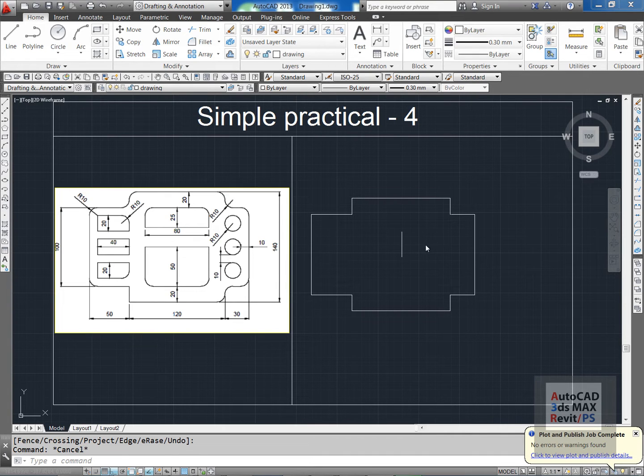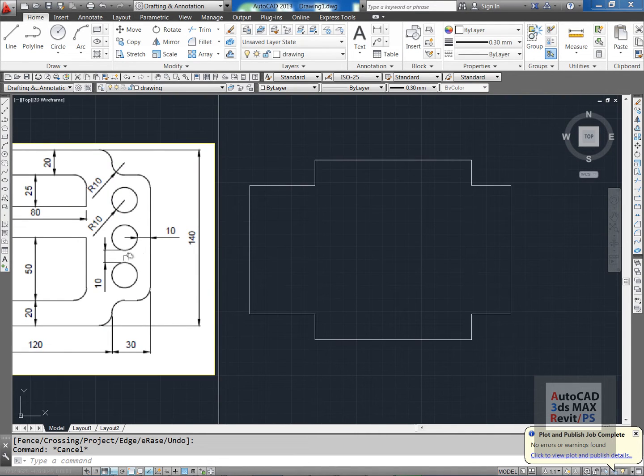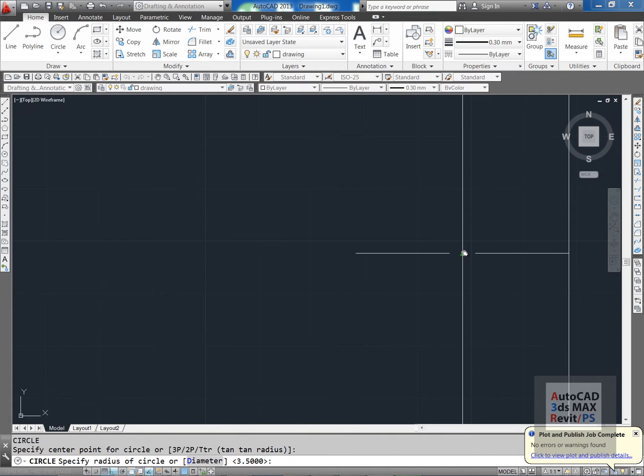So this is how you have made the outer structure of your drawing, and now we will see how to make these circles. For making these circles I will make the view a little bit bigger. Now making this circle, there is a little trick which you have to remember. I will start with this center circle. I will make one line from the midpoint of this. Now you can see the radius of the circle is 10. When the radius is 10 and from here to here the distance is 10, the radius will be another 10. So that means the center of this circle from this point is 20: radius 10 and this distance 10, 10 plus 10, 20. So I will make an offset of 20. I will reach this center point, and I will make a circle of radius 10.